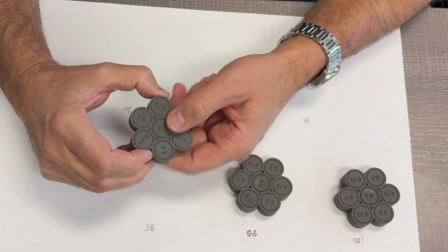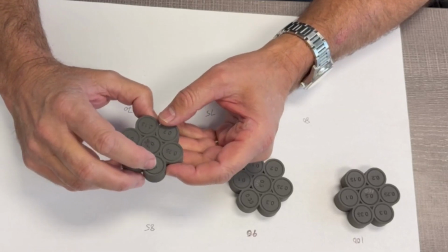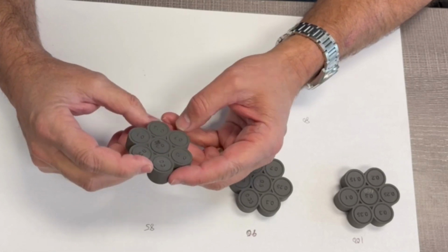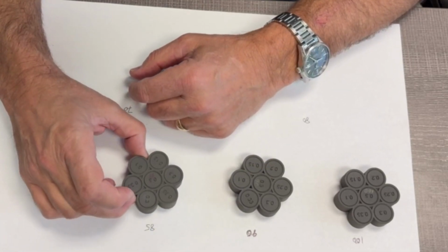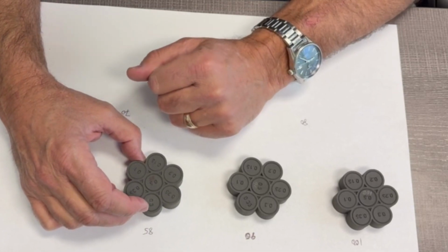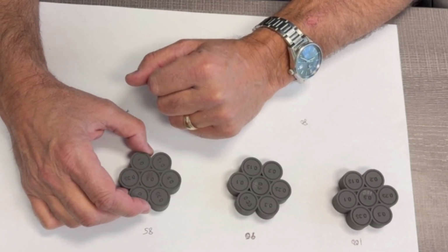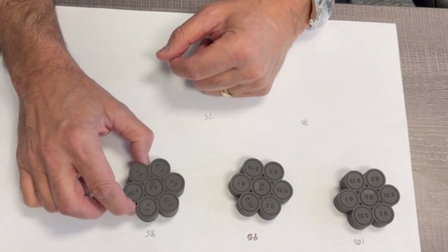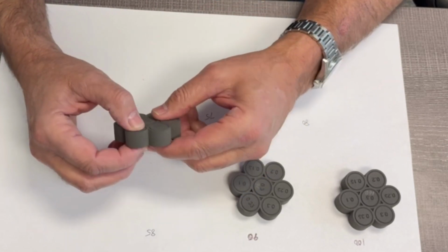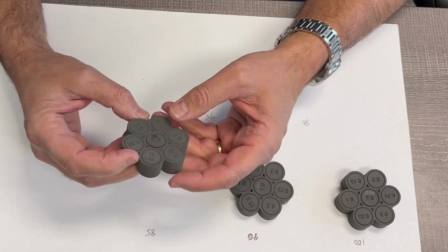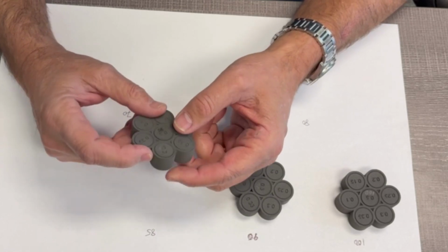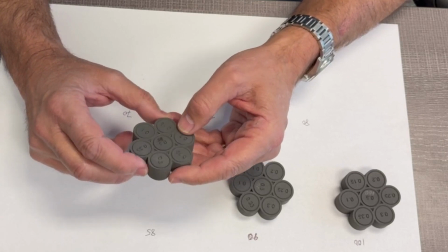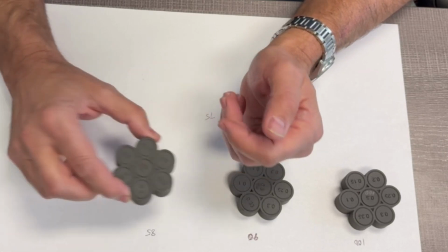So at 85%, I finally got the 0.3, but you can see it's the slot there. I cranked on it pretty hard as well. So we were just starting to get to the 0.3. Now in SLS technology, they say 0.3 is what you should design through. 0.3 millimeter is the design tolerance. But that was so tight, and I didn't want to have to, if I'm printing functional parts that maintain a 0.3, as you get unsintered powder in there, it's hard. It takes a lot of effort.